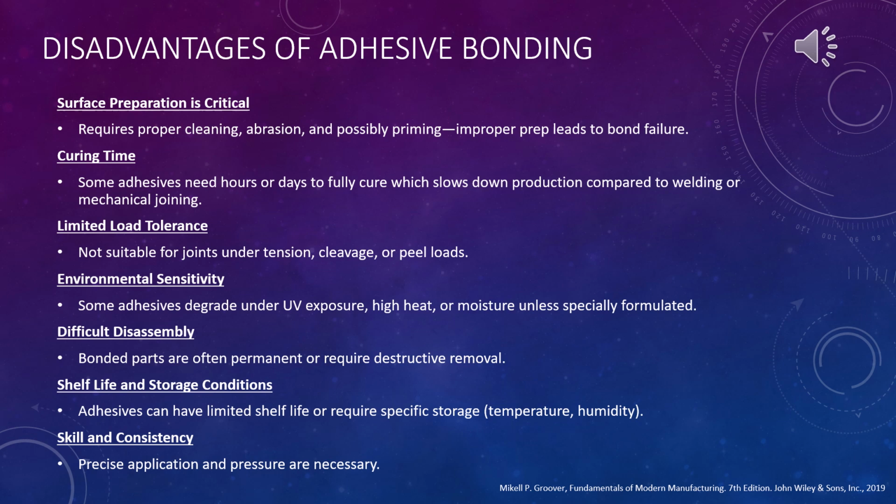Number 6 is shelf life and storage conditions. Adhesives have a limited shelf life or require specific storage, temperature, and humidity. They can expire and lose effectiveness over time, especially if not stored properly, and many require specific humidity and temperature control, which adds logistics costs. Some are two-part systems with limited pot life once mixed.